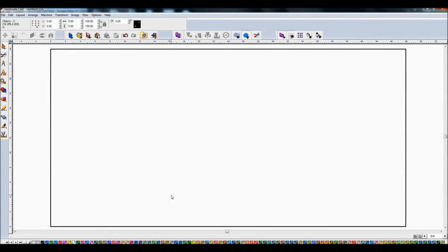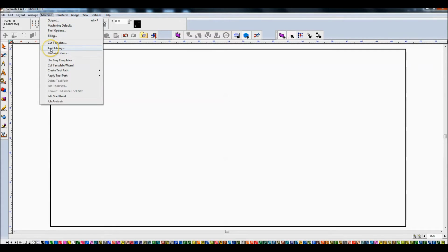In this tutorial, I'm going to cover basic setup in the CAD and Driver software in order to set up multi-tool support such as your plasma and plate marker for Torchmate tables. So the very first step that I want to cover is going into your tool library inside of your CAD software. What you do need to do is set up a tool specifically for your plate marker.